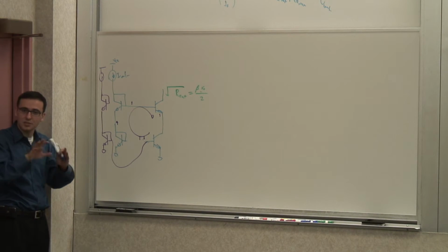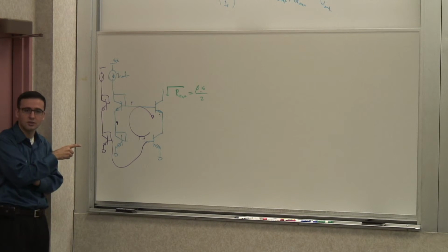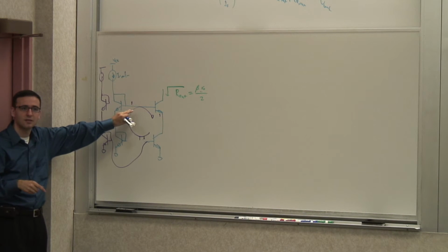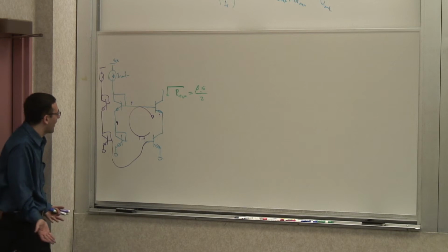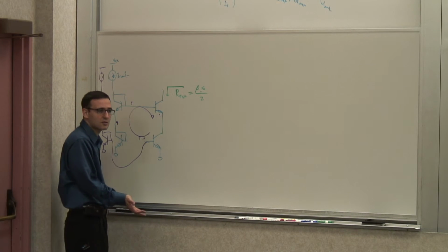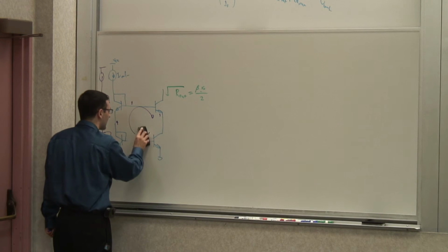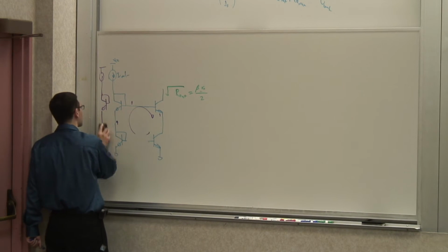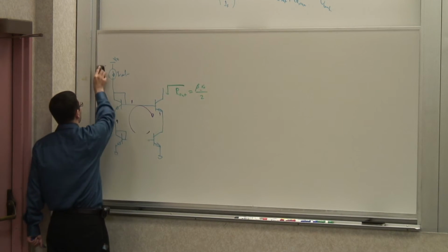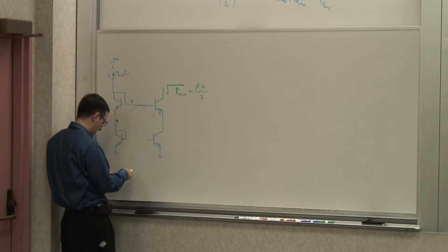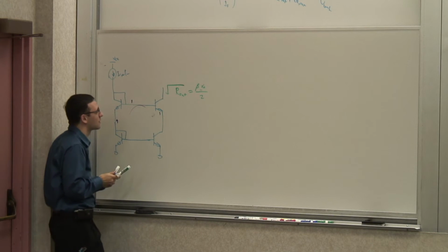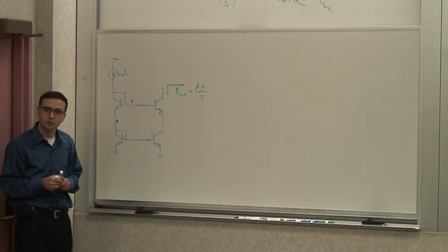So you generate these two voltages independent, so they're not coupled to each other. These two voltages do not affect each other. If you do that, you get beta RO. That's why I say it's a trick question, but there's no way to know actually what the answer is before you write the equation. But there is some tricky thing there. But nobody does this. Because beta RO over 2 is large enough as well. So for practical purposes, that's good enough. Okay? So it's beta RO over 2.